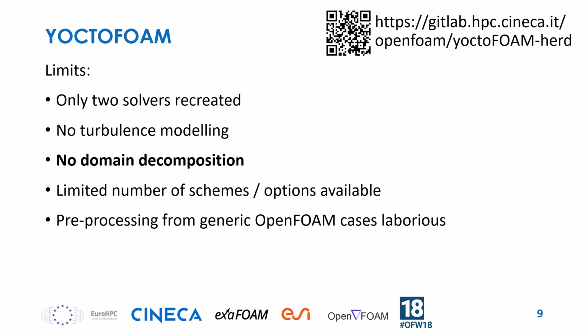YoctoFOAM is not a replacement for OpenFOAM, of course. It has many limits. It has less than a fraction of all the options and functionalities of OpenFOAM. We only recreated two solvers. You cannot run turbulent cases. Everything is laminar, and you cannot do domain decomposition. This will be relevant later on.